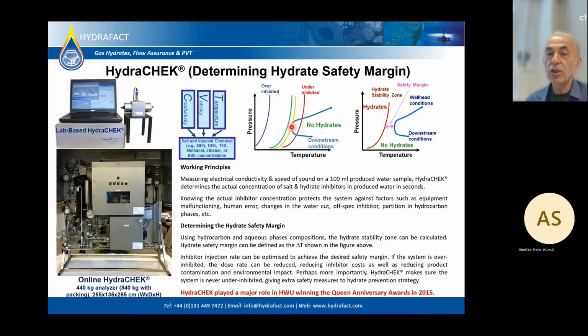But you can imagine at the design stage, first of all, reservoir pressure is much higher. Secondly, those people do not want to take any risk, so they propose higher inhibitor injection. And for various reasons, normally they inject more than what is required.